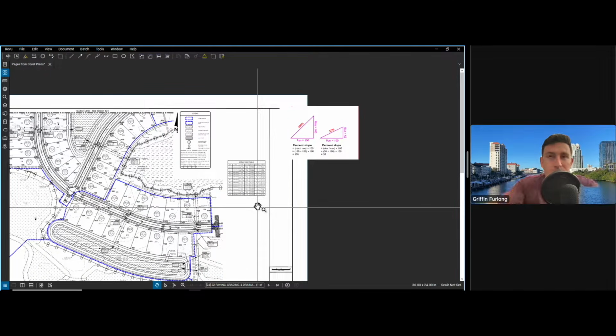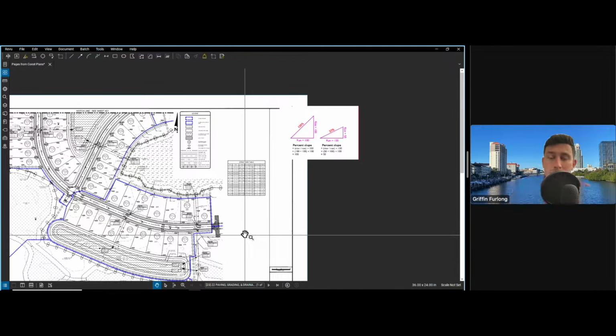It just so hit me that, just walking around my neighborhood, I was able to get a whole bunch of information. I actually took my phone out and would measure the different slopes. So I started understanding what a steep slope was. What was steep? What wasn't steep? What was an average slope? Once you start building those foundational building blocks of seeing something visual, you can then easily apply it to a set of plans. So that's definitely my number one golden tip for young engineers out there. Just study the world around you, get out your phone and understand the different slopes that are out there. Start measuring sidewalks, start measuring road slopes, measure a pond.